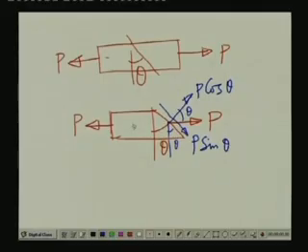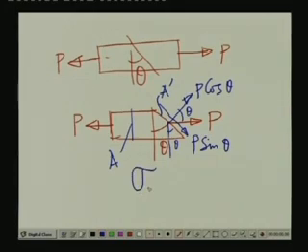Now, if we say that the cross sectional area here is A and the cross sectional area of this is A dashed, then the stress acting on this inclined plane, the normal stress sigma theta, theta being designated by this particular plane which is cut at an angle of theta with respect to the vertical, is sigma theta equals the normal force component, P cos theta, divided by this area A dashed.